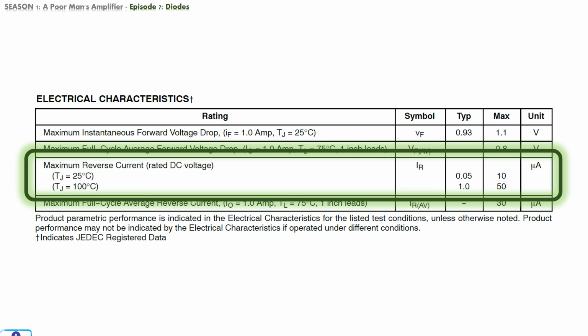So, we will have to infer that this specific parameter was obtained when DC voltage was cycled from 0 to maximum volts allowed for this specific diode. In our case, we are using the 1N4001 diode, and its rated maximum operating DC voltage is 50 volts. Fortunately, this parameter is listed in another section of the datasheet.